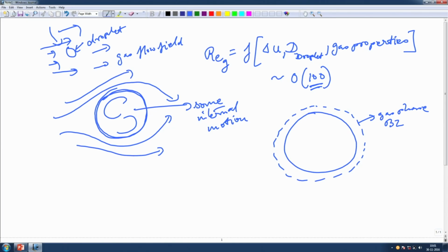If the gas is air, the gas phase Prandtl number will be of the order of 1, so these two boundary layers will perhaps coincide with each other. So, you can have a gas phase boundary layer, thermal or momentum or viscous. This Reynolds number value therefore creates that kind of a boundary layer effect.